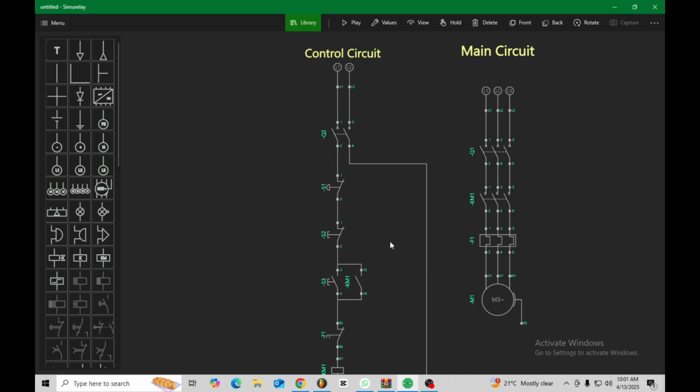Now, remember, this looks simple right now, but it can get to a point where it's complicated, where you have multiple contactors that must be sequenced and started in a certain sequence. For instance, maybe you want the main one to switch on, then the main must switch the star on, then it must change to delta, then maybe after a certain amount of time, motor 2 must turn on, and whatnot. Now, if your connections are wrong and you did something wrong on this, you could potentially cause a horrendous short. That's why we put this protection circuit here to protect the motor, and all these other things will trip in case of that.